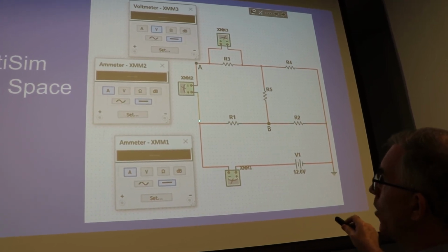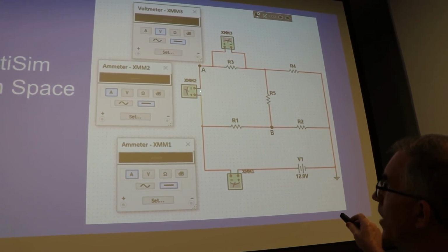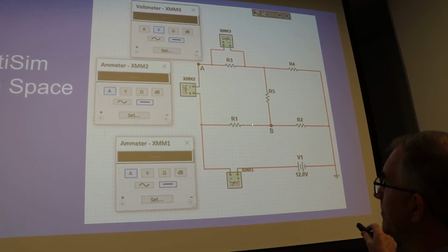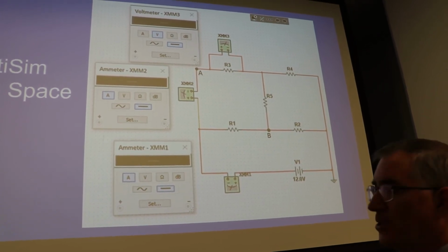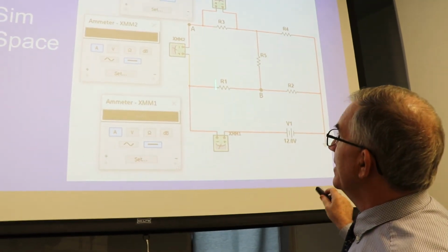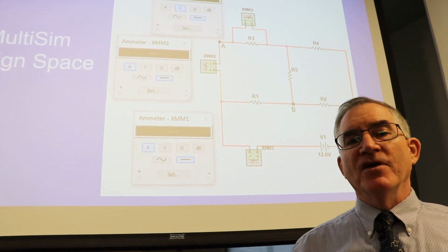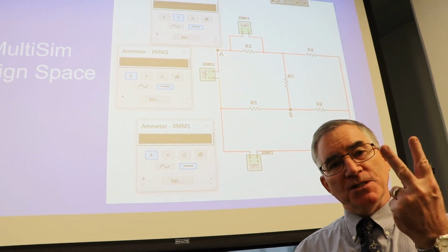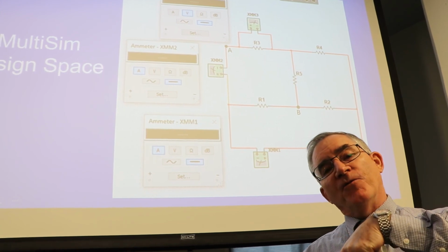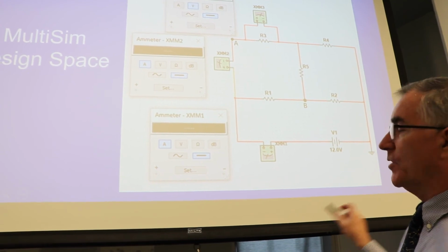So by the way, any wire that's in contact has the same voltage. So you see all this wire is connected all along here. So you can put your voltage probe right here and then touch right here. Okay, and that'd be the voltage across AB. It's called voltage AB. All right, you're going to do that for the first experiment, and then you're going to do it when you change that R5 to a battery. So now you're going to have 2 batteries in the circuit, and then you're going to redo Kirchhoff's rules, put it into the 3 unknown equation solver, and then see experimentally what you get.